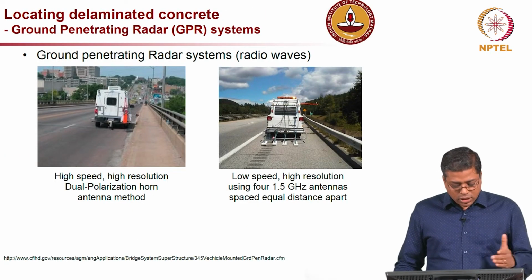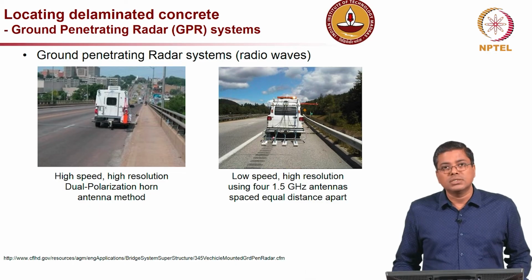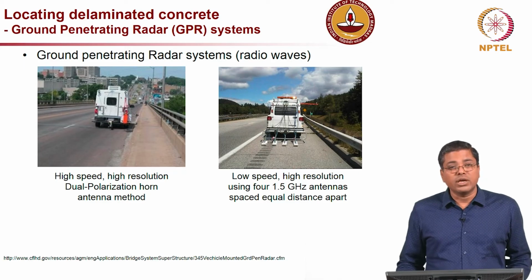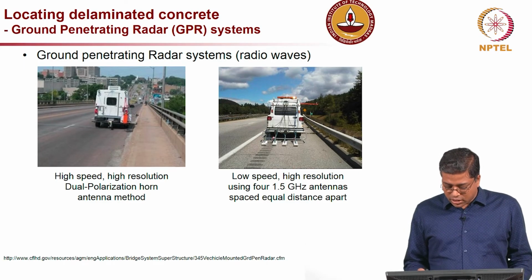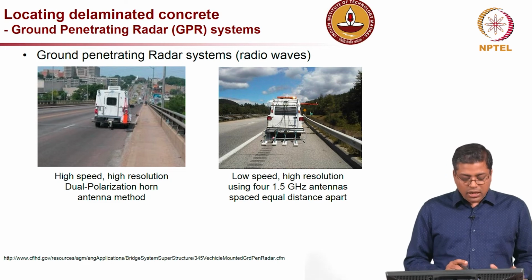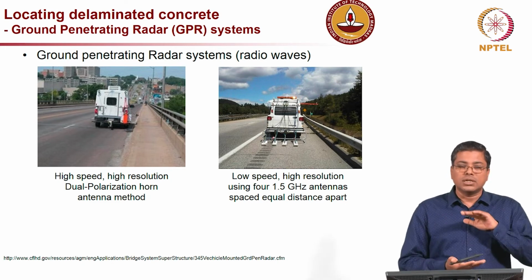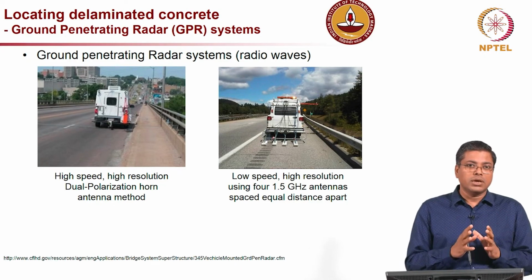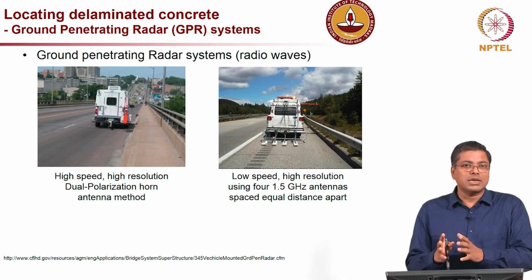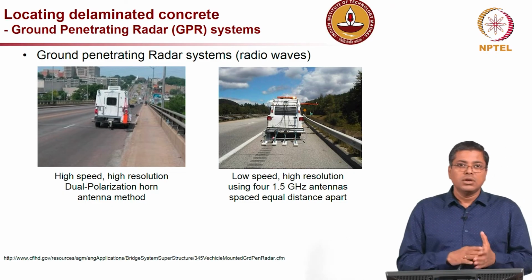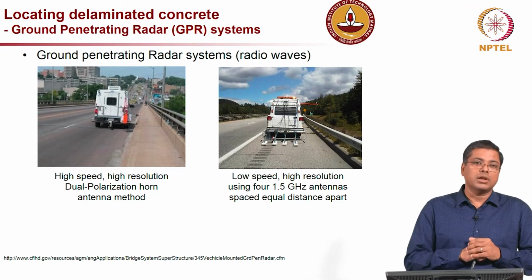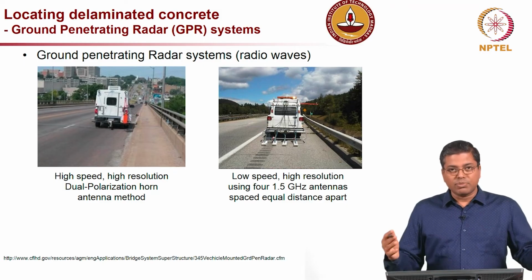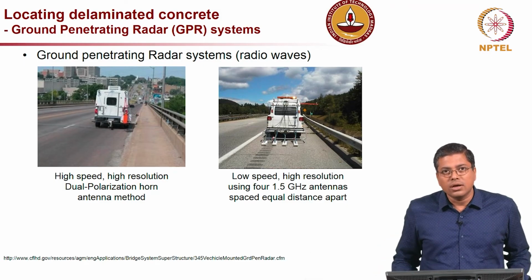Now, again looking at other techniques, there are GPR systems, or ground penetrating radar systems, which come in different frequencies. When you talk about this kind of tools, it is very important to look at whether that particular instrument is able to take good measurements on the particular structure, looking at the thickness of the structure or the cover concrete. So, that is very important. It is not that all GPR systems will work for all concrete structures.